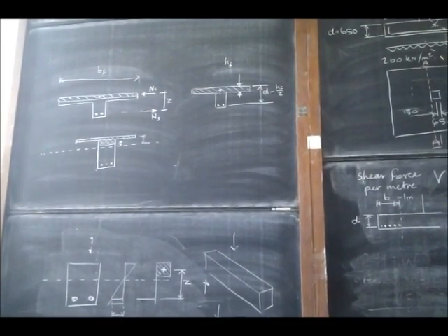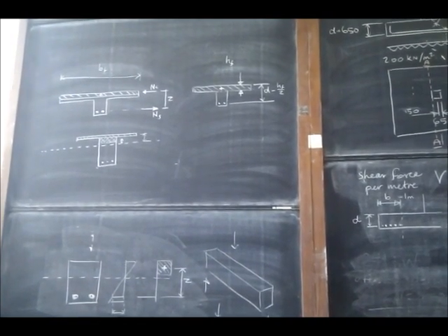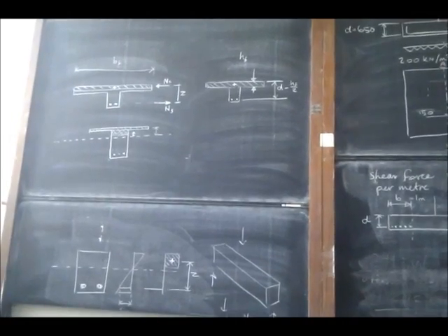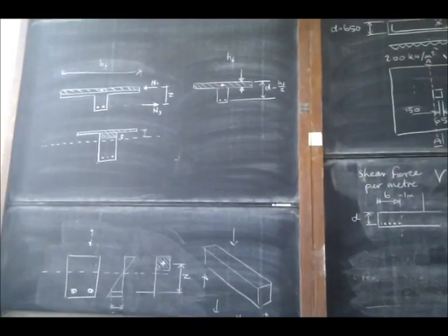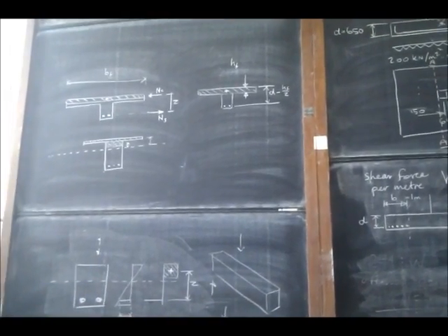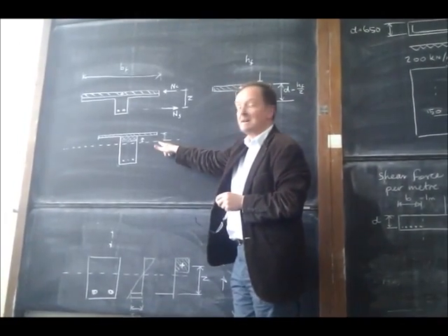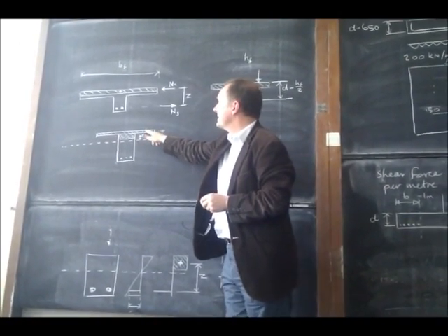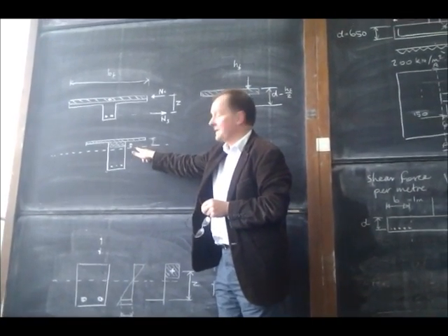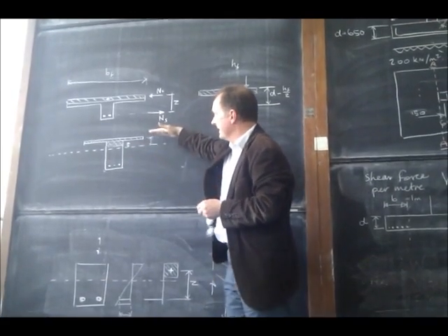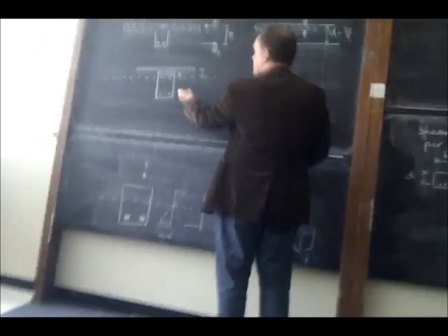If you use spreadsheets for designing reinforced concrete beams, then they'll generate an exact answer for you. But we're not in that business. We're looking at the basic principles, some rudimentary calculations to be able to check the sort of computer output that we're going to get. So this is where the neutral axis lies well into the web, and so there's some contribution from the web as well. Can't go too far with this one though, because if that neutral axis comes further down, then we're going to get into the situation where